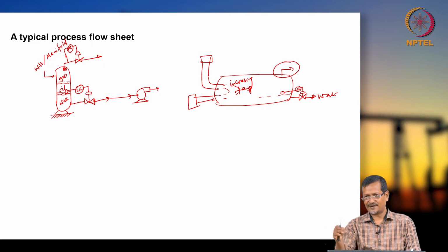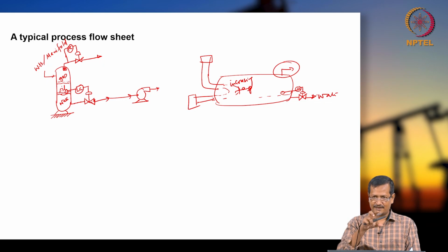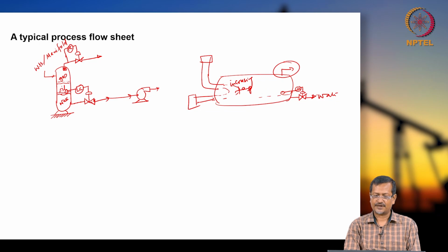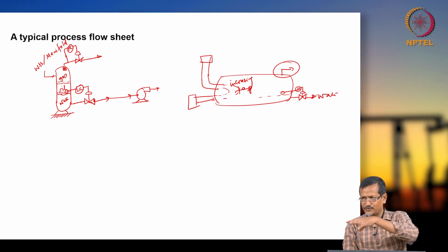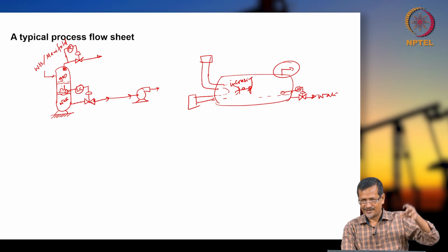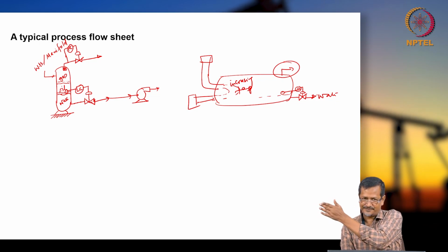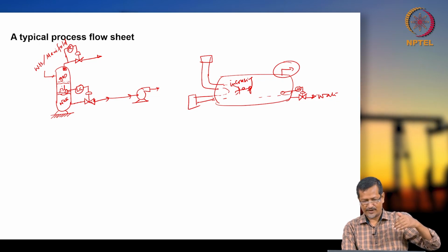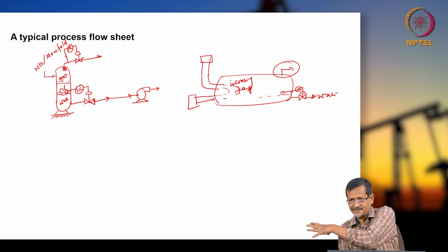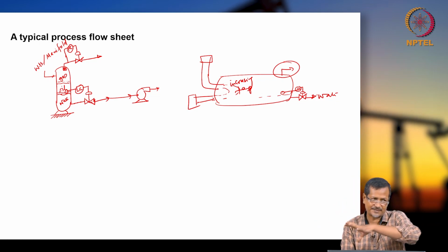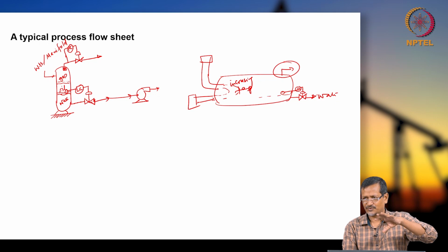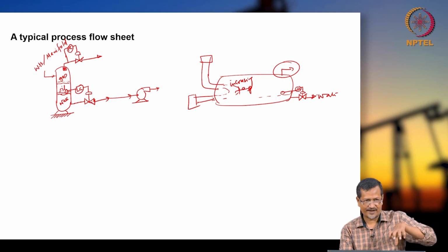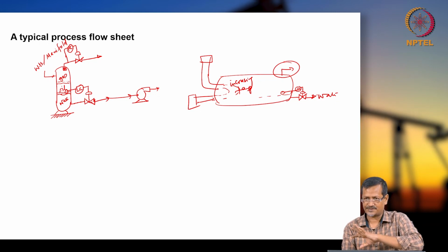Then you put it into a separator and separate. If you have different wellbores with different pressures, you cannot make a separate system for every wellbore. First you have to make a unification, put everything in a single separator, then handle everything together. If well 1 has 1200 psi pressure and well 2 has 500, having a separate separator system for each is not possible, it will be too expensive. So you have to make only one system, and all wellbores will be connected together via a manifold. That will be the best process.